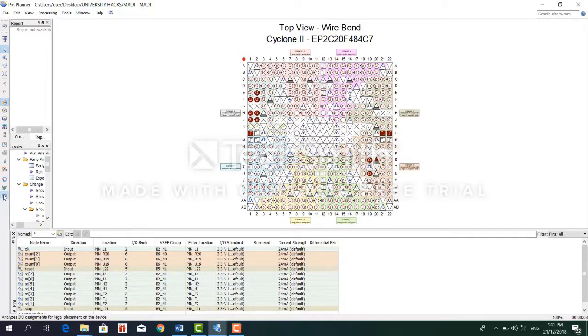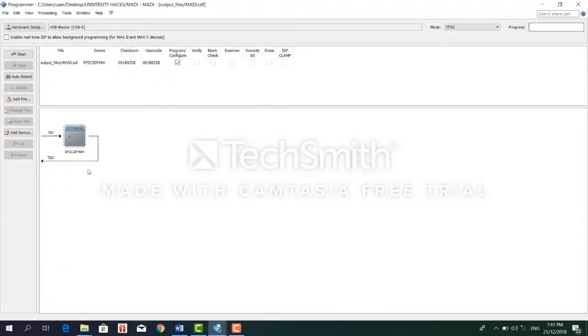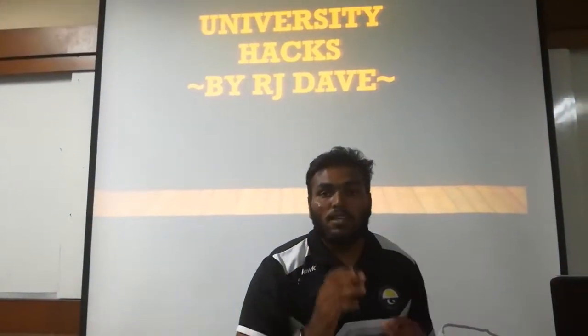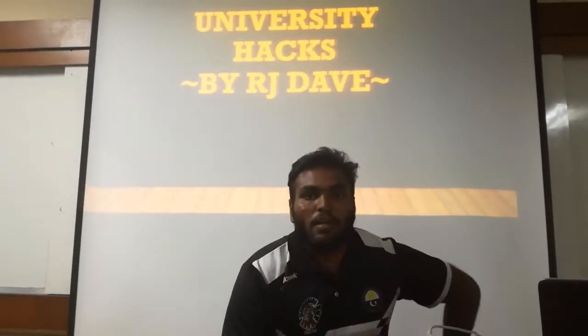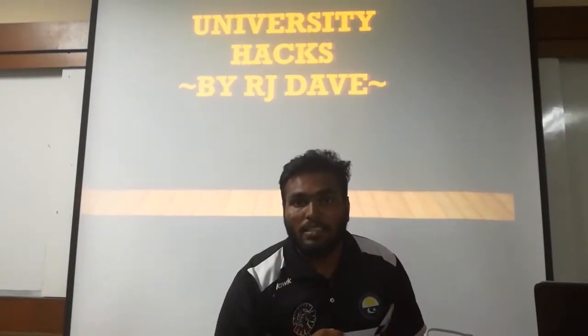Once the pins are assigned, you can compile. Next, click the programming icon to upload the programming. So here you can select the file and you can start uploading your program once your hardware is connected. So students, Mr. Vanan has shown you a very brief explanation on how to pin plan the input and output positions, and also how to upload the coding into the Altera board. And he was already working on the Altera board to show you a perfect example of the hardware setup.